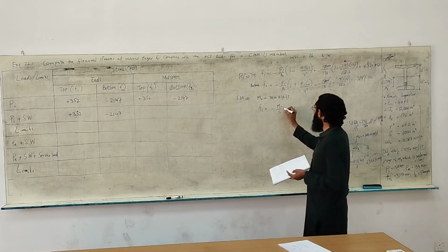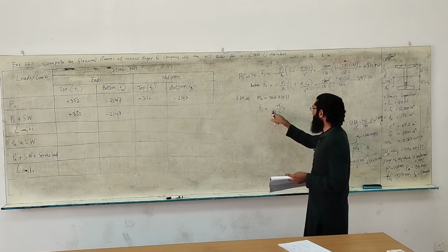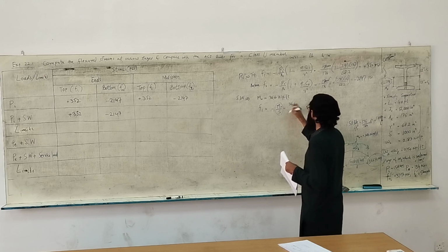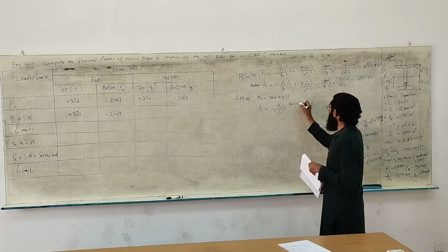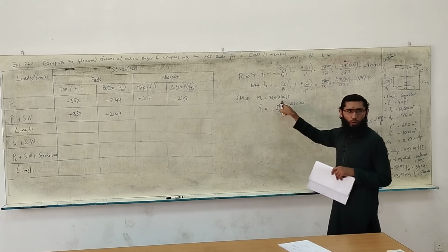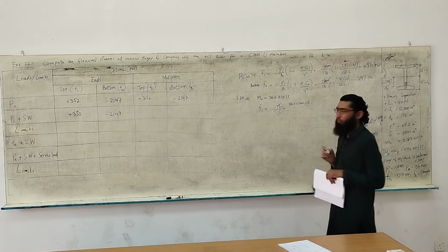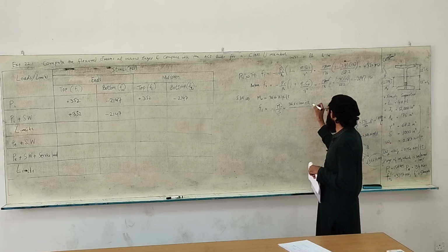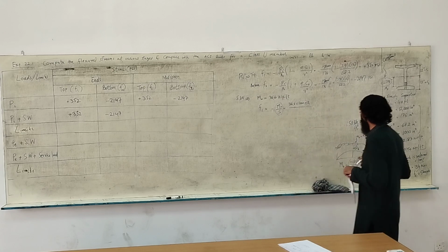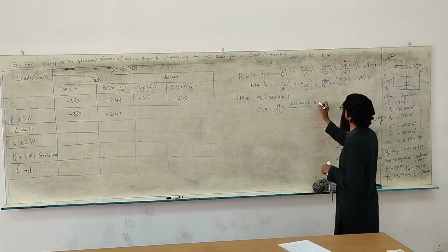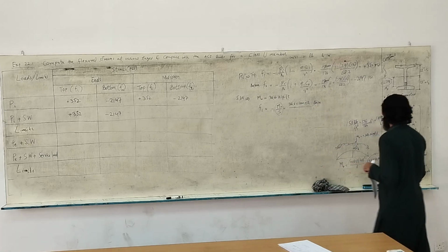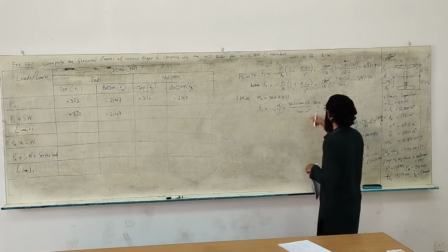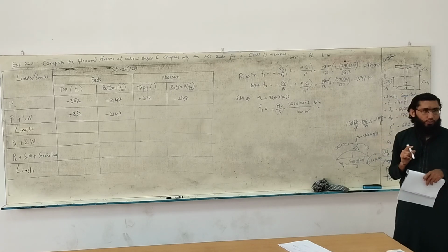Okay, so this is giving me the numerical value, and this is taking care of the sense. Now M naught is 36.6 kip-foot, so I will multiply this number by 1000 to make kip to pounds, and feet I'll use 12. So now the moment is in pound-inch, and S is already in inch cubed, so 1000 inch cubed. So you can see we will end up with pounds over inch squared, which is psi.